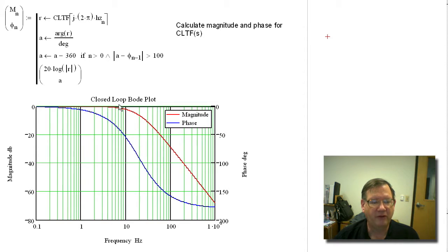It would also have a little hump here because of where the gain exceeds 1, and that's due to the zeros. And the phase would be closer to 0 all the way out to about 4 hertz or so. So you get almost perfect tracking with the PID, but with the lead lag filter, you can see that there's a little bit of lag much earlier.